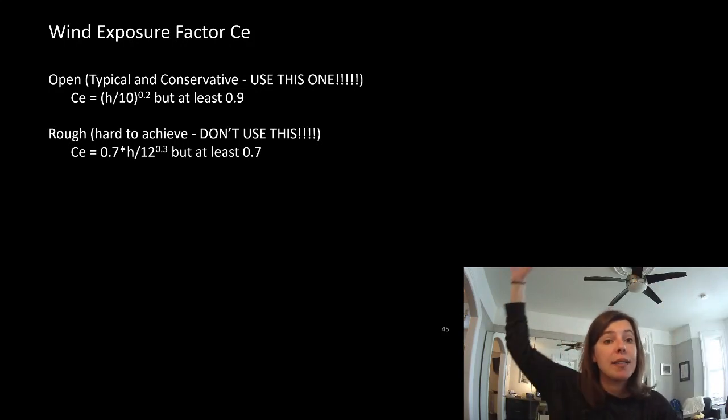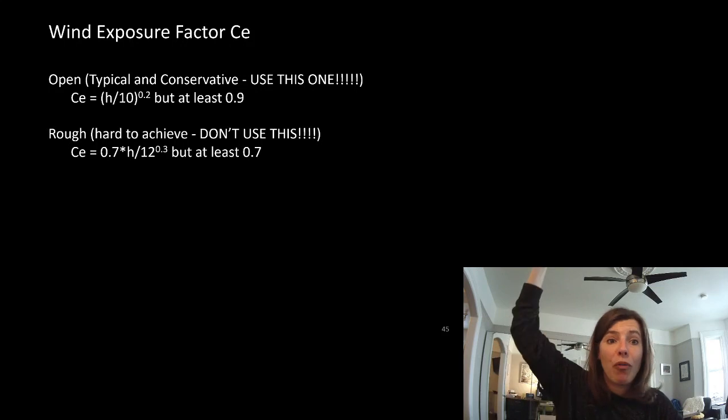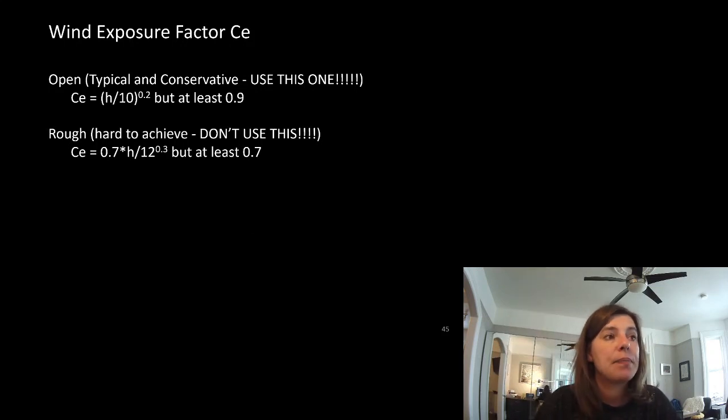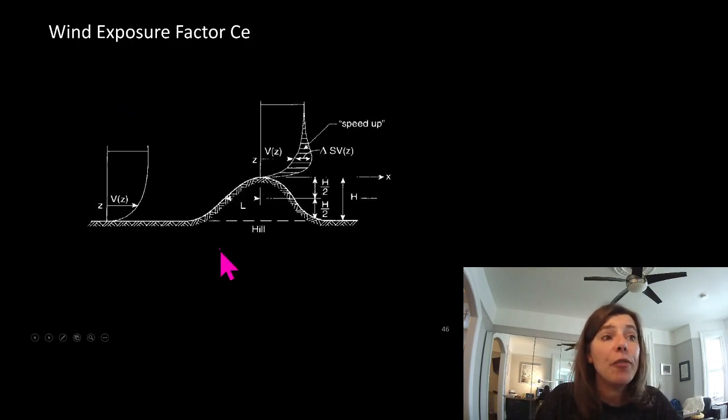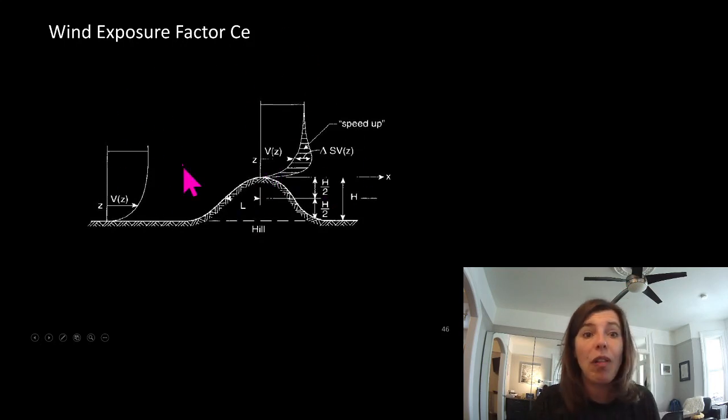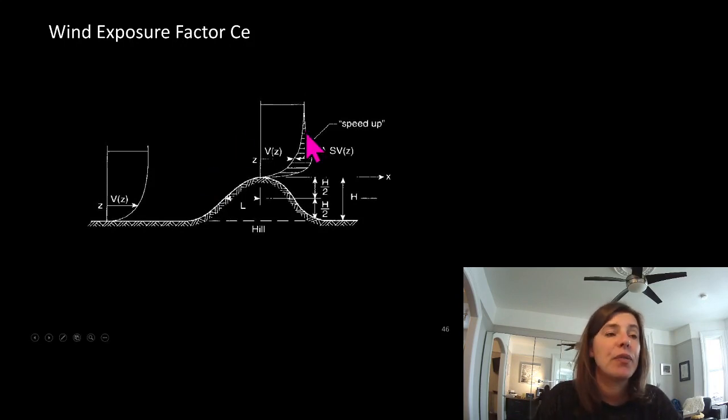So a high rise, you can end up with like 1.4 high on a building. If your building is perched on the top of a big hill, you would have to treat it like it was that far off the ground. Because this is kind of like lifting your building up off the ground. So there are exposure clauses for tops of cliffs and big hills, for example.